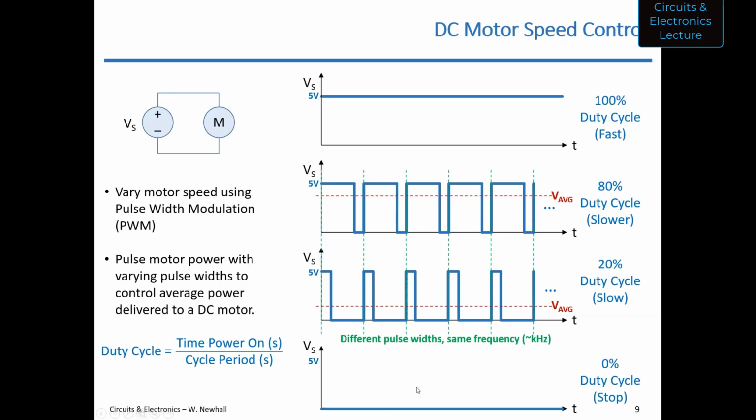As you apply pulses, the rotor speeds up, but as the pulse goes low, the rotor does start to slow down a little bit, but before it can apparently slow down, it's hit with another voltage on pulse. So it has the effect of being a low pass filter.